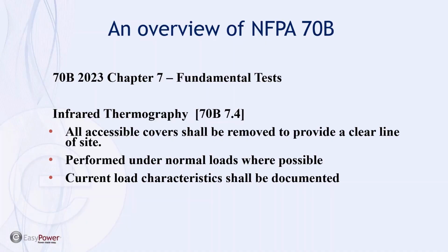Today, an appropriate infrared survey by the standard would require that the various covers and protected devices be removed to provide a clear line of sight to the various terminations and connections within the electrical components, so that your test subjects are visible. Without the removal of those panel covers, many of the terminations of the panels would be inaccessible to the true infrared assessment. And therefore, what kind of test are you doing if you're trying to use an infrared camera through a protective cover? It doesn't work.